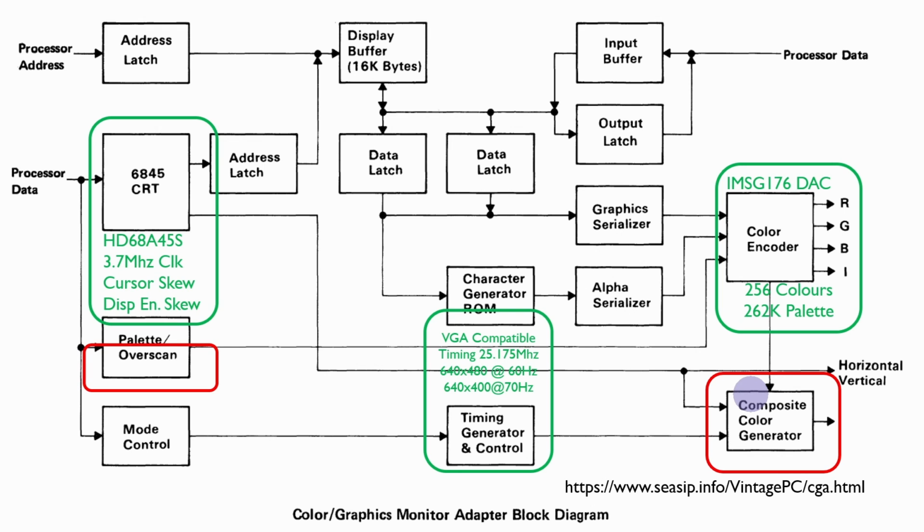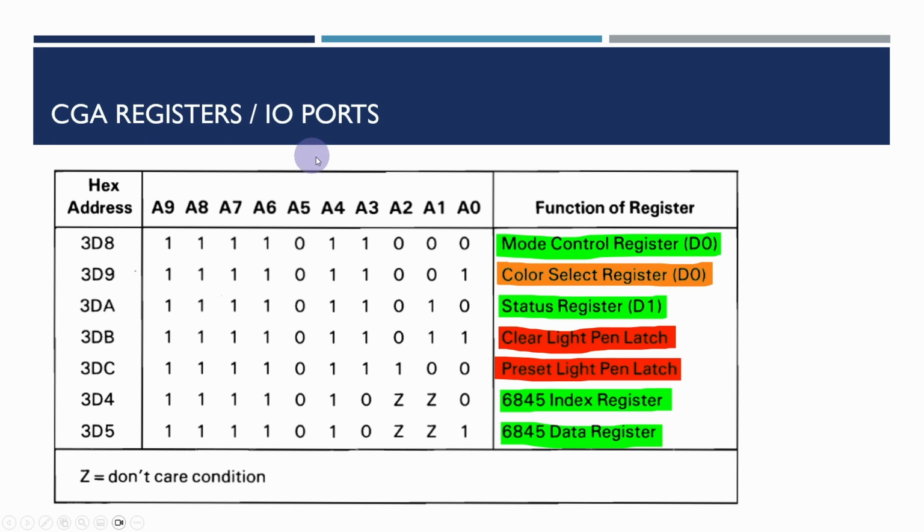So there's quite a bit of logic in the output involved in generating the NTSC color compatible chroma signal, which is added into the composite output. By not including that, it will simplify things quite a bit, and it'll also mean that the output stages and the text mode side of things are going to be almost identical to the monochrome display adapter that we've already done. So these are some of the outputs from the technical documentation that I'll be referring back to.